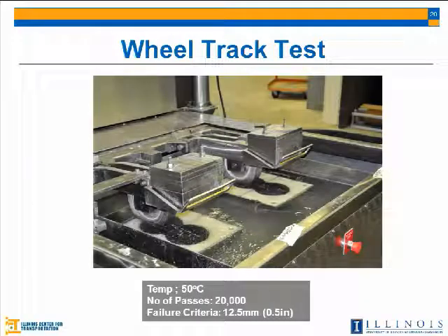When water penetrates asphalt pavement, and that water freezes and goes through freezing and thawing, contracting and expanding, it can break the aggregates, resulting in the end in stripping and separation of the asphalt pavement. Yeah, so that means moisture damage is causing aggregate degradation, not the other way around, right? Aggregate degradation is not causing it. I think you are right.